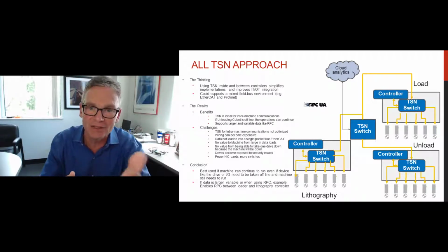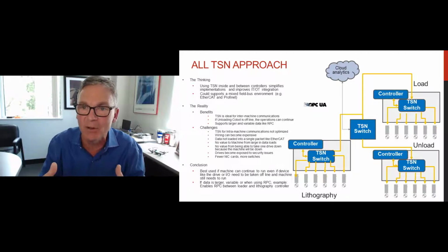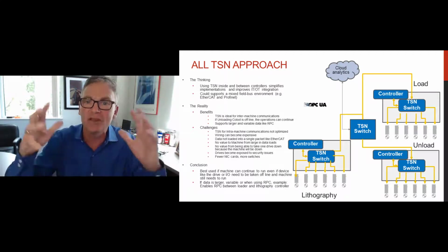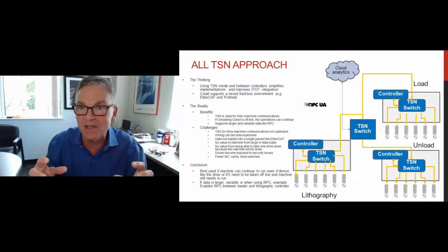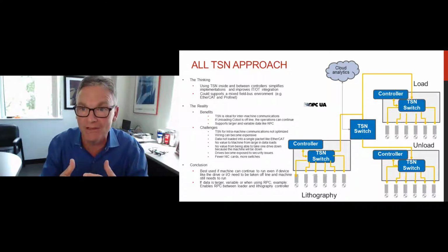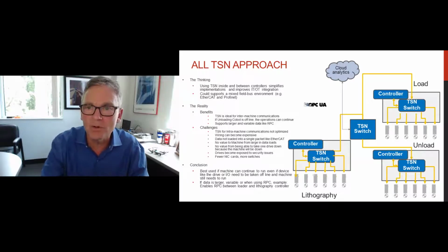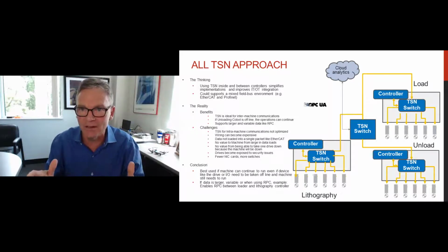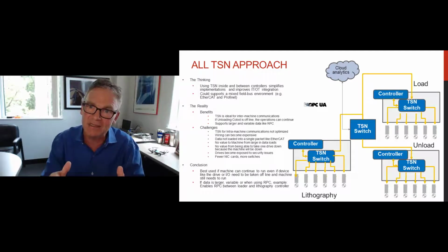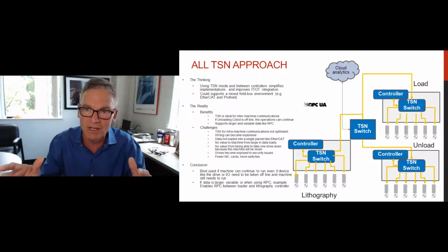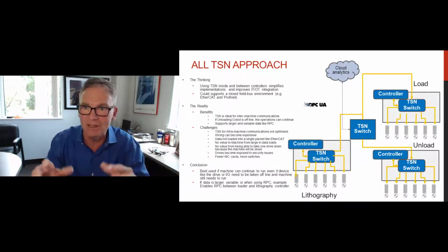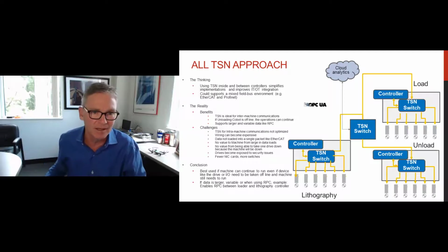And all you're doing is adding, look at all this networking that you're adding. It's a huge amount of networking. You have to add a lot more switches. The costs start to go up. And by the way, TSN is not a protocol, so you have to do all that integration work. So if it were the case that one of the motors could go down and your machine continues running, then yes, TSN might be a really good answer for you. But if it's the case that inside, one of the motors goes down and the rest of your machine can't continue running, then it doesn't make sense to add TSN.